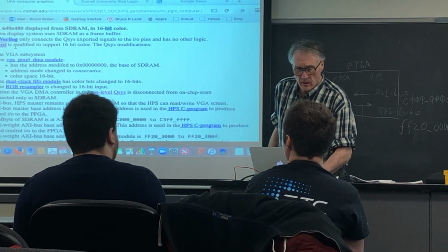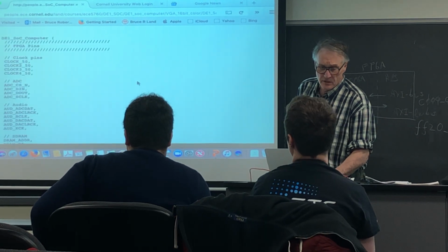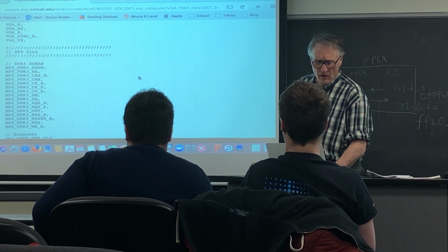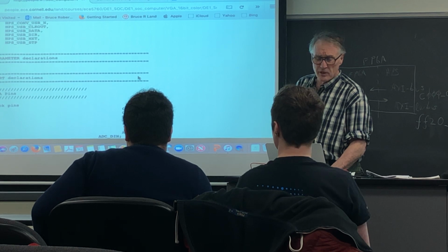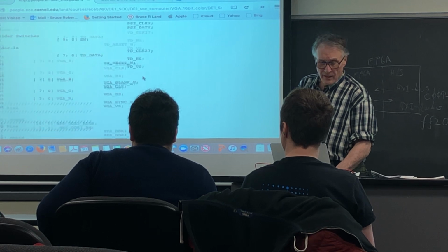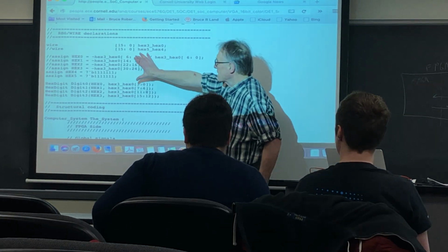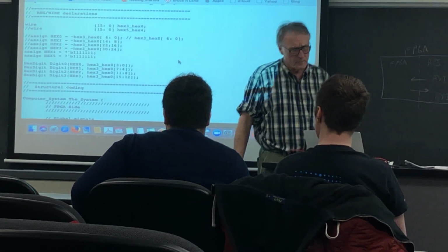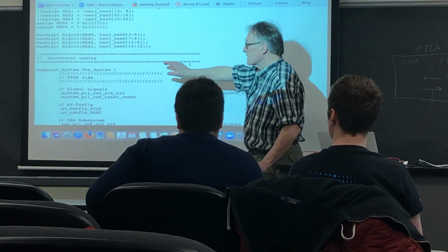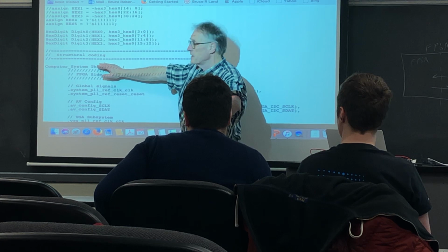big internal structure. Then the top level Verilog. This is going to be the module that you have access to and can write into, put modules into. It's going to have a very long list of I/O pins because the FPGA is connected to all kinds of stuff on this board. Whole bunch of I/O signals. I wired up some of the hex displays because I was using them for debugging. And then the module which is exported from Qsys is instantiated in the top level module.